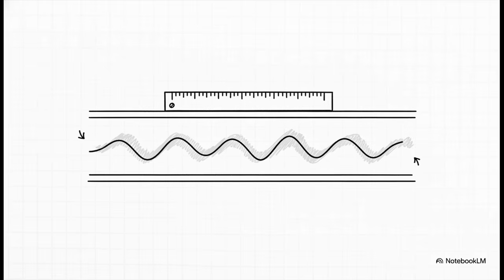Oh, and as a really important side note, the standard also specifies that if you attach the straightness symbol to a size dimension of a cylinder, it can uniquely apply to what's called a derived median line, which is essentially the abstract imperfect centerline of the feature. But for basic surface straightness, just remember, one line bounded by two parallel lines.